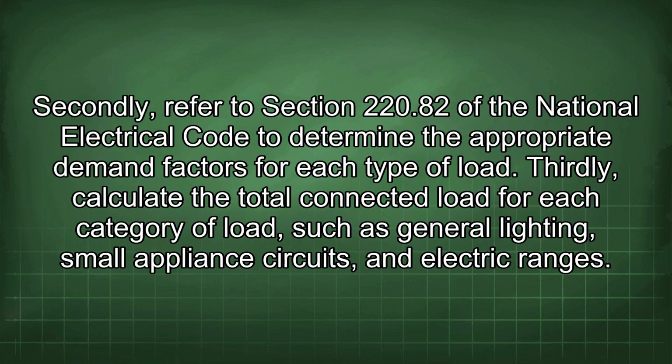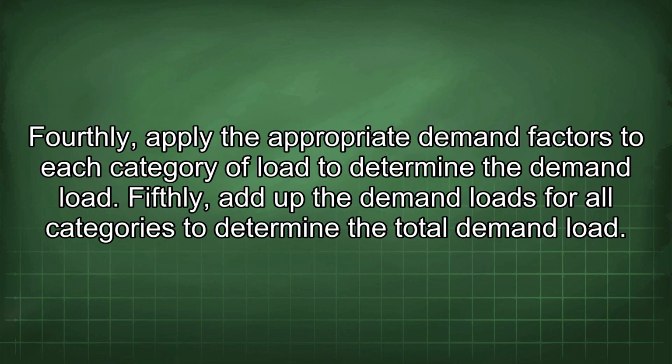Secondly, refer to section 220.82 of the National Electrical Code to determine the appropriate demand factors for each type of load.